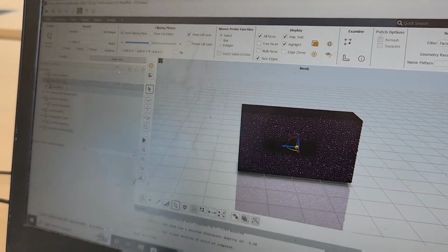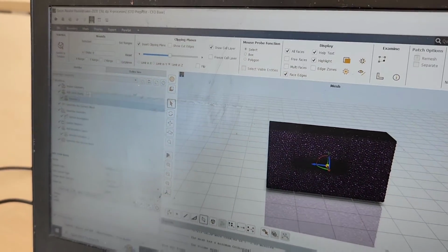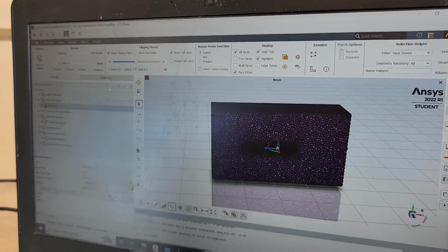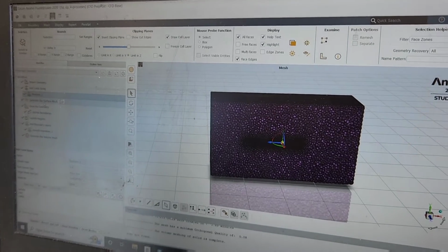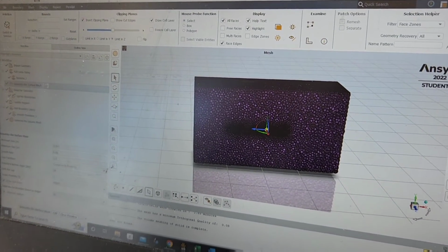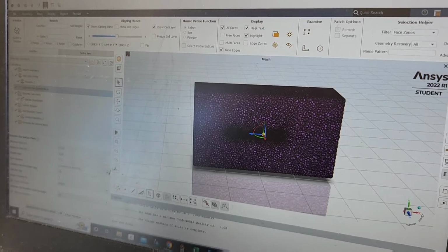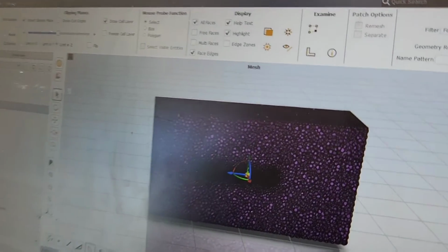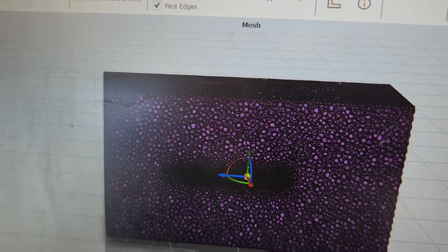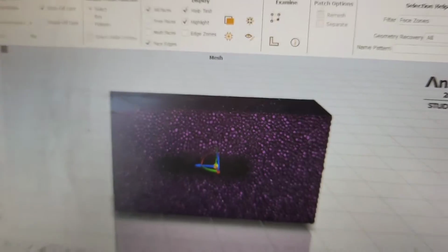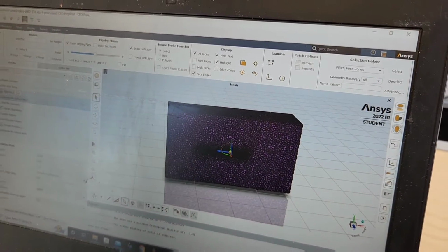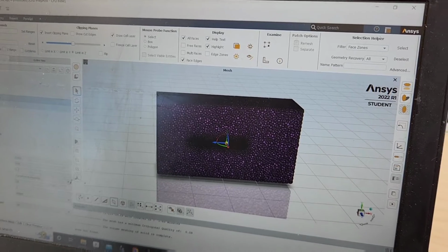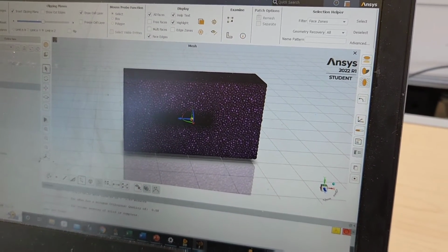For us, we chose to add a small local sizing just around the perimeter of the body of about 3.8 millimeters. Then you create a surface mesh, and you can see what we used here. The only thing is that these sizings have to align with the minimum and maximum values chosen for the generated volume mesh. From there you describe your geometry.